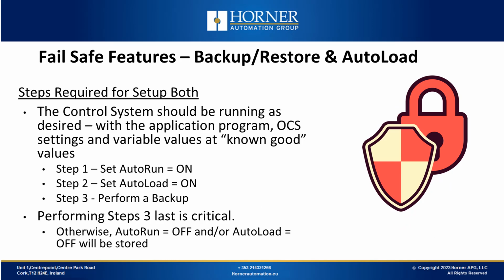Now we'll demonstrate this failsafe feature. It's important to note that while backup and restore, as shown earlier, is unquestionably the most crucial failsafe feature, autoload does serve a valuable purpose. It safeguards against situations where you might lose your program, such as during an interrupted download, perhaps due to a remote download over the internet with a sudden loss of cell connection. This can leave your controller without a valid program, and autoload steps in to automatically load a known good program at the next power cycle, ensuring recovery.